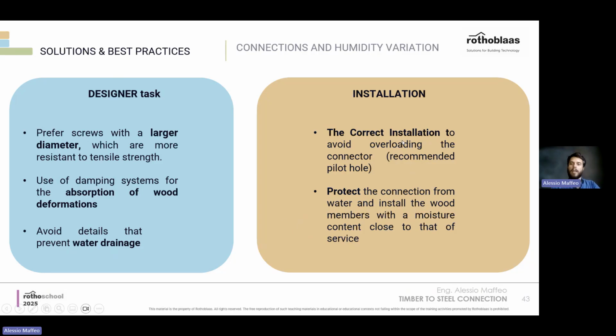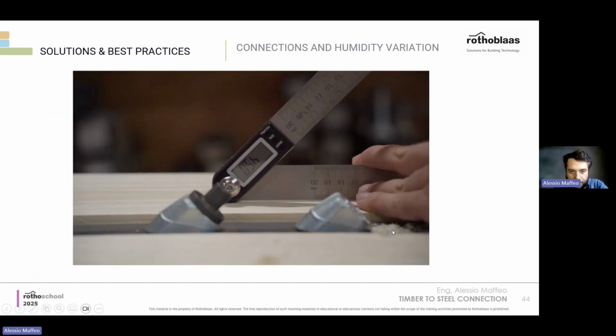The installation has to be correct without overloading the connections. We want to make the pilot hole, also to have the right direction. And we want to have no impact drill, especially in the last point when we touch the plate. You can use the impact drill just as long as you stop before reaching the plate. Protect the connection from water and install the wood members with a moisture content close to that of service.